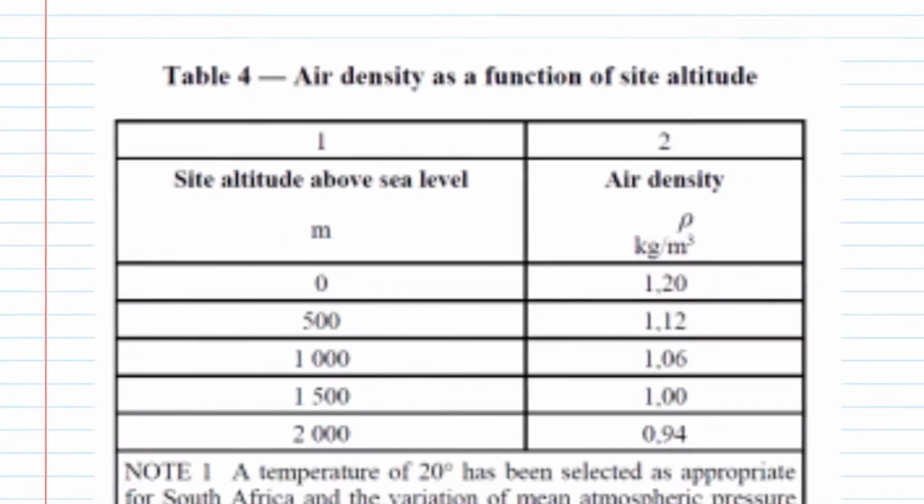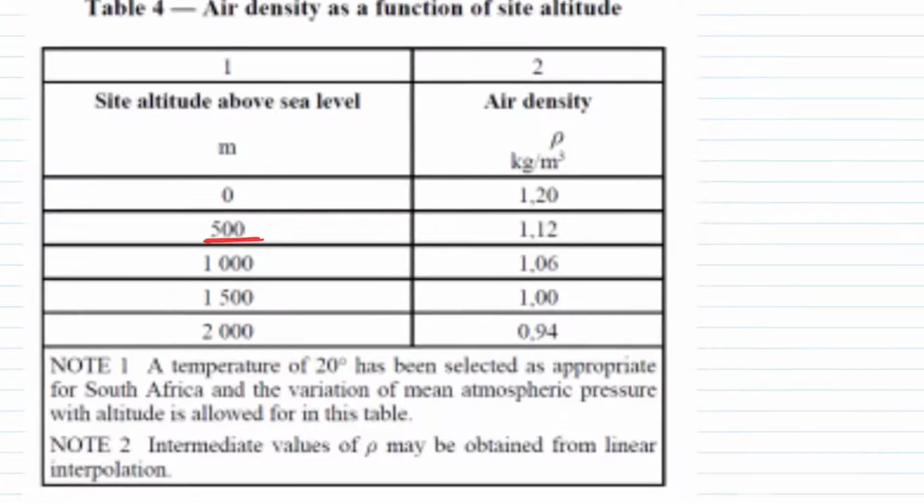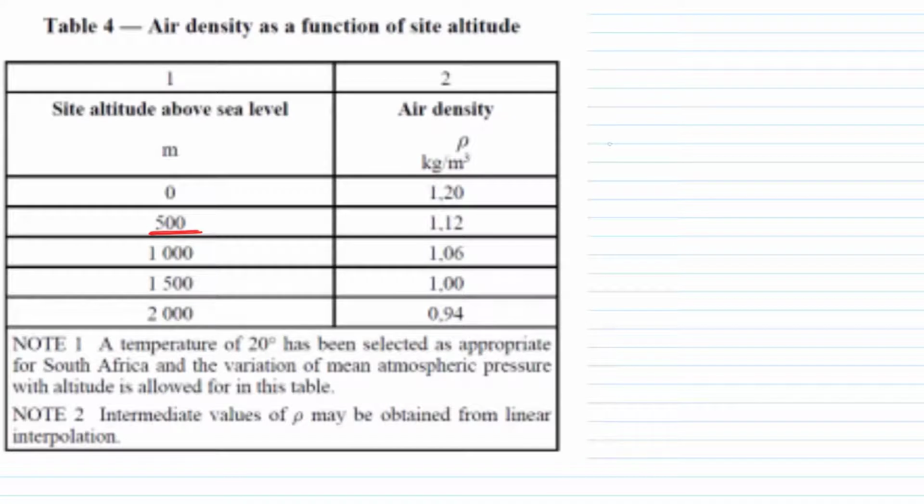And so we've got our air density. We need to know what is our altitude above sea level. For instance, we are at 100 or 200 or 1,000 meters above sea level. You would then use this, interpolate between the values, and to be honest, you can ignore structure height normally. You can see these are not big changes in value.